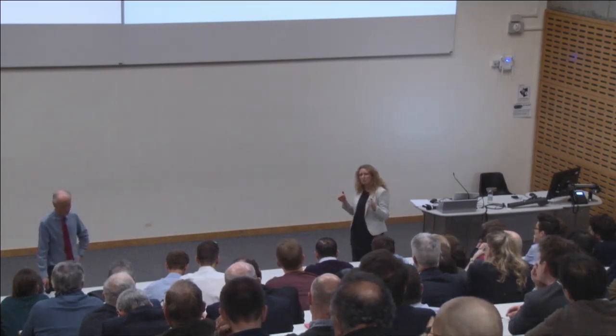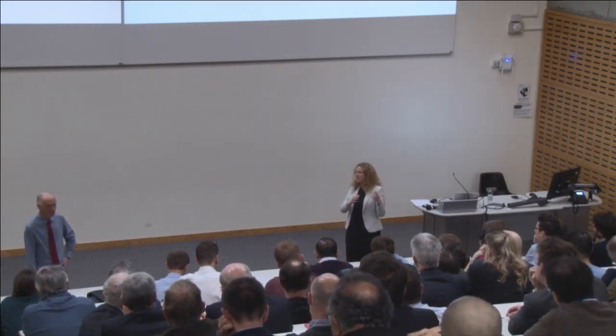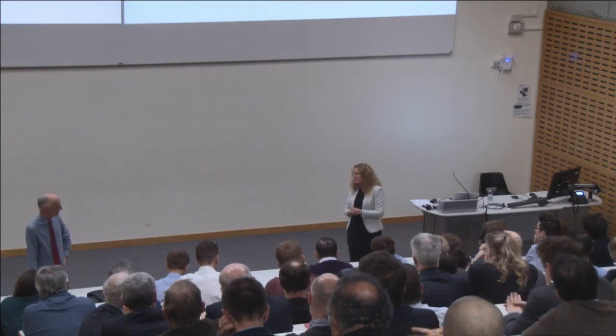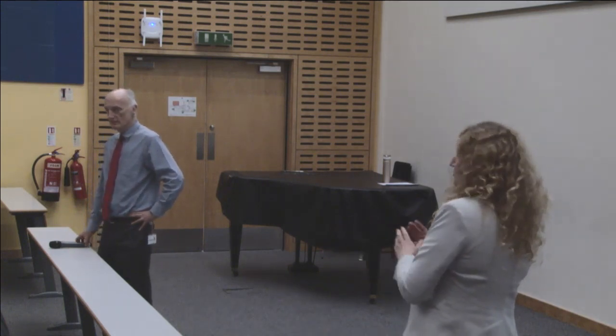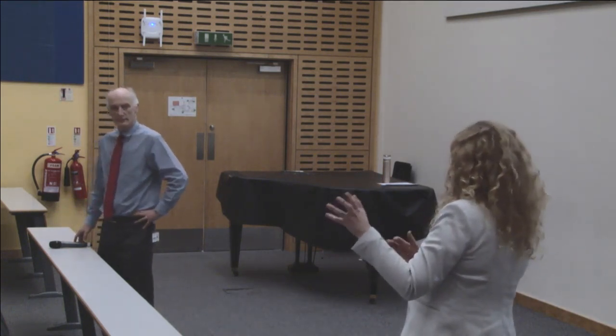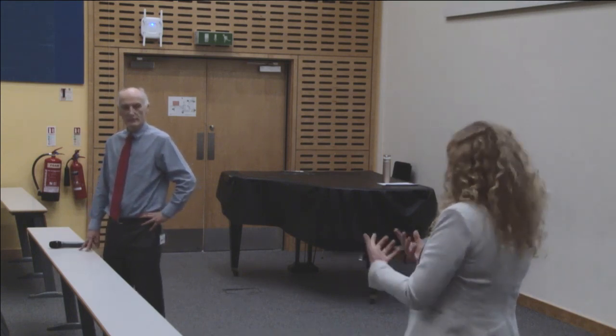Yeah, so I think there might have been a bit of a rush to satisfy one driver without carefully thinking about consequences, in this case for fire safety. And it can't be that we just give up on energy performance of buildings and rush off to think about a single driving parameter now, which is fire safety. It's about the careful consideration of both. And there is a way of using polymeric insulation safely. It just has to be thought about properly and detailed up and installed properly in a building. So it's about the careful consideration of conflicting risks, if you will, or conflicting drivers.